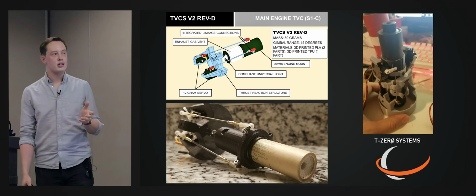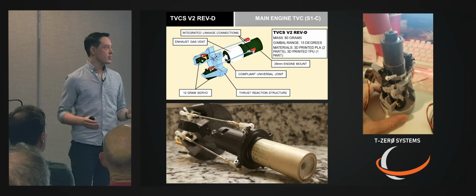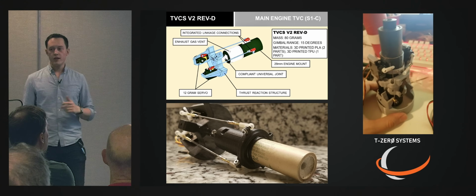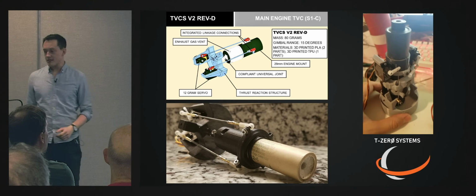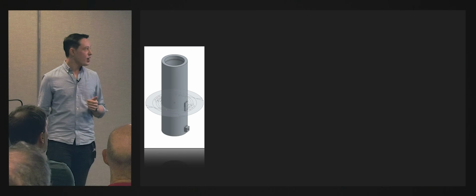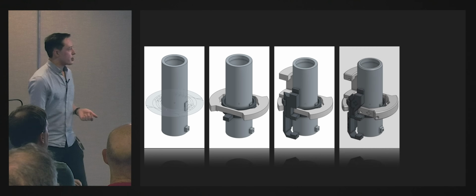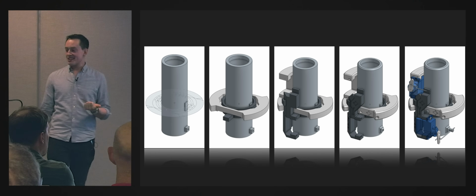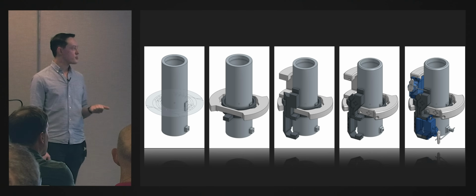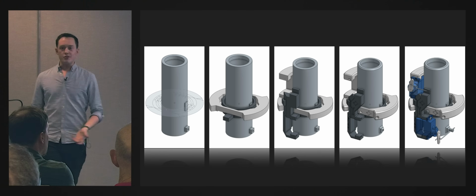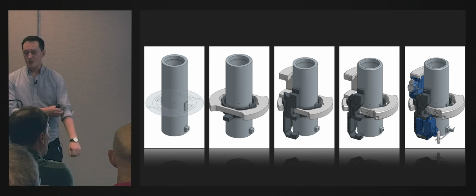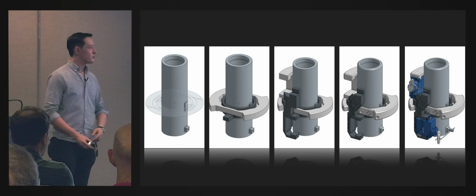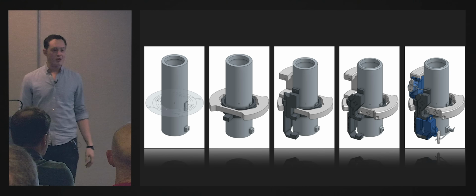but a compliant gimbal means there are no hinges at all. It's all rubbery plastic that's hinging, so you don't get the degradation of any metal from exhaust products of the motor or something like that, which is pretty cool for TVC systems. And then finally, this is just a slide from last year's talk. I wanted to re-emphasize the importance of iteration here. It's going to be really hard, just kind of like the clips that I showed earlier of the failing rockets. It's going to be hard to get it right on your first try. So if you're building something like this yourself, don't get too down on it. It's going to take a couple of tries to get it right, and it certainly has for me. And then this is a small little advertisement, but if you want any of these files, they are available for download on the BPS website.